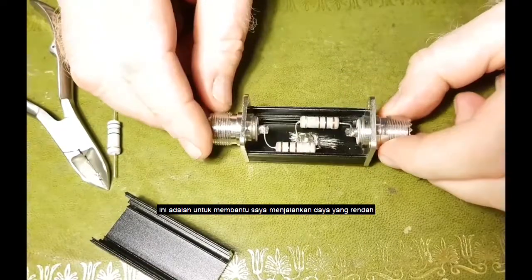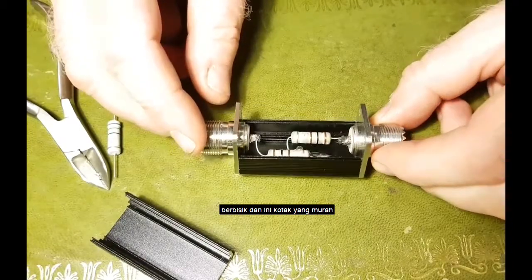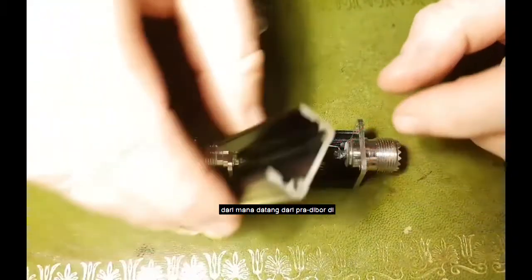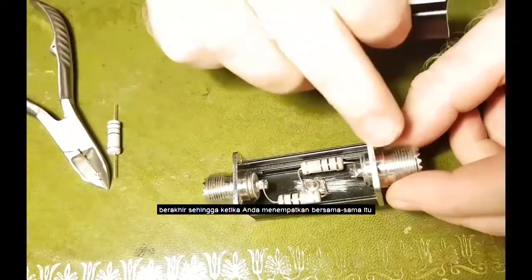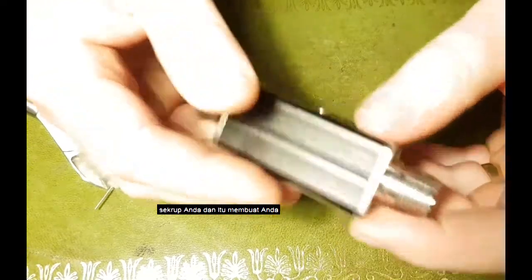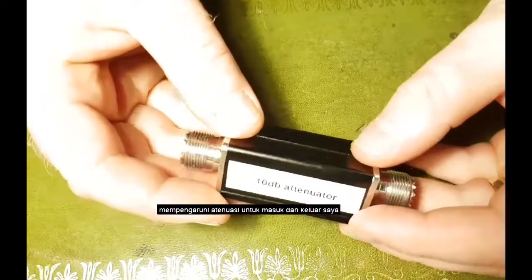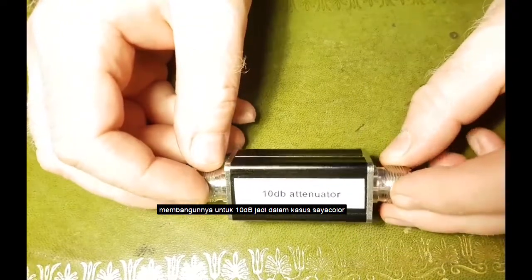Basically, this is to help me run lower power on Whisper, and this is a cheap box bought from eBay. I'll flash a picture up on the screen so you can see where it's from. It comes pre-drilled on the ends so that when you put it together it will fit SO239 sockets. It just drops into place and snaps in, you put your screws in, and that makes you an attenuator. Obviously it will affect attenuation between in and out. As you can see, I'm building it for 10 dB.